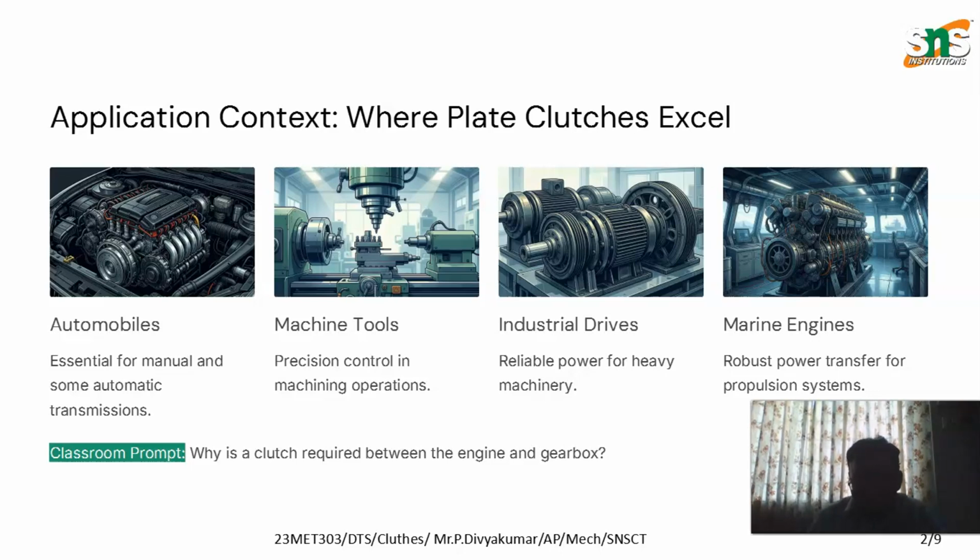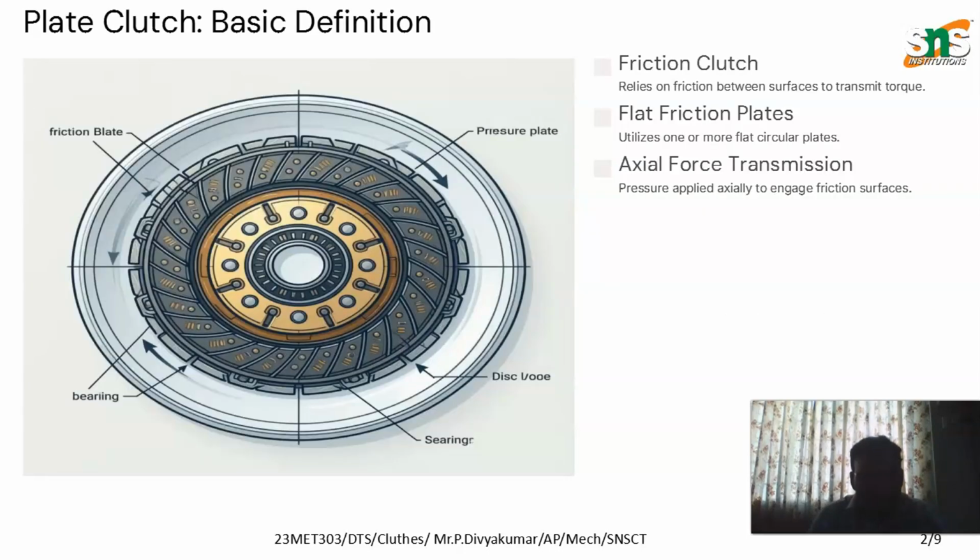Next, we are going to discuss the working or basic definition of the clutch plate. When the clutch pedal is released, the pressure plate presses the clutch plate against the flywheel. This leads to transmitting power. Pressing the pedal disengages the clutch and interrupts the power flow.